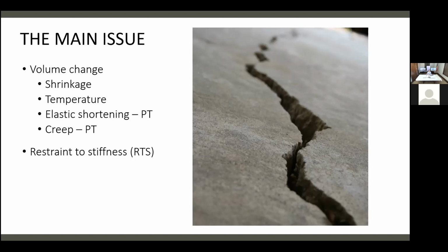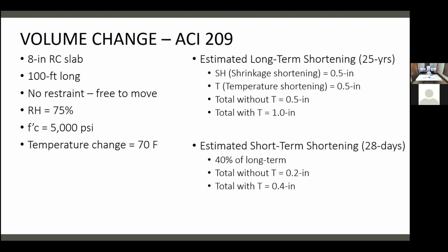But restraint is something that's not very well understood and not something that our computer programs do well for us, as helping us identify the stiffness and strengths. Everything in your structure has restraint, even columns that aren't part of your lateral system.